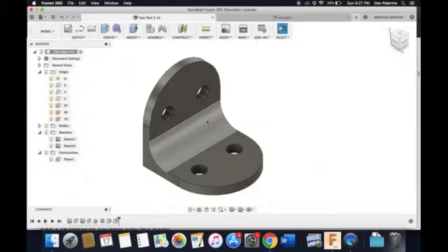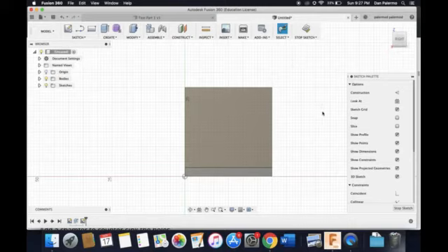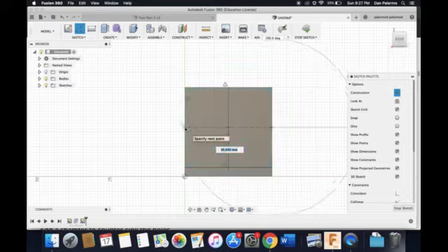Now, if I go back to here, you can see that these two holes are symmetrical from either edge. Okay, so I'm going to come back here. What I'm going to do is click on this construction tool icon and create construction lines so I can kind of find my middle. So I click on that, and now I press L on my keyboard for line, and I find my midpoint here, click, down to here, straight down, click, and then I'll find my midpoint here. There it is, it snaps with that triangle indicating that's the midpoint, and there.